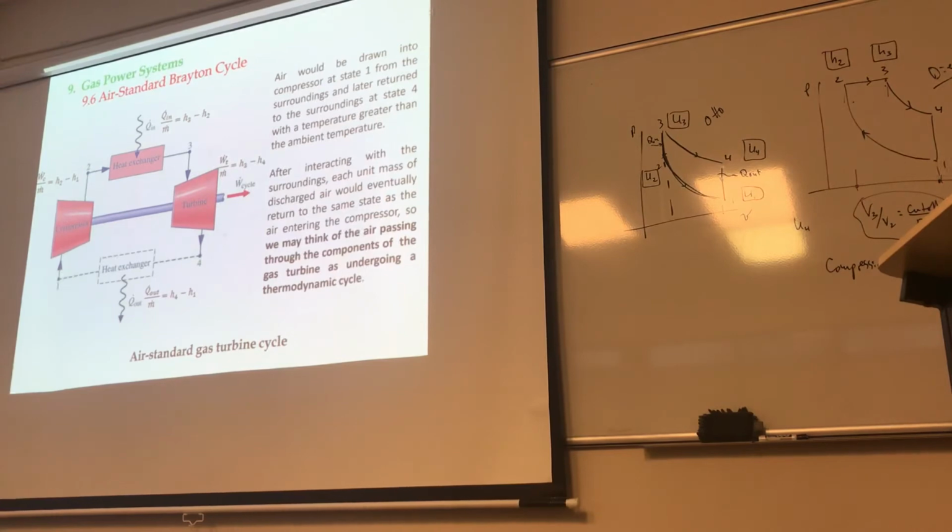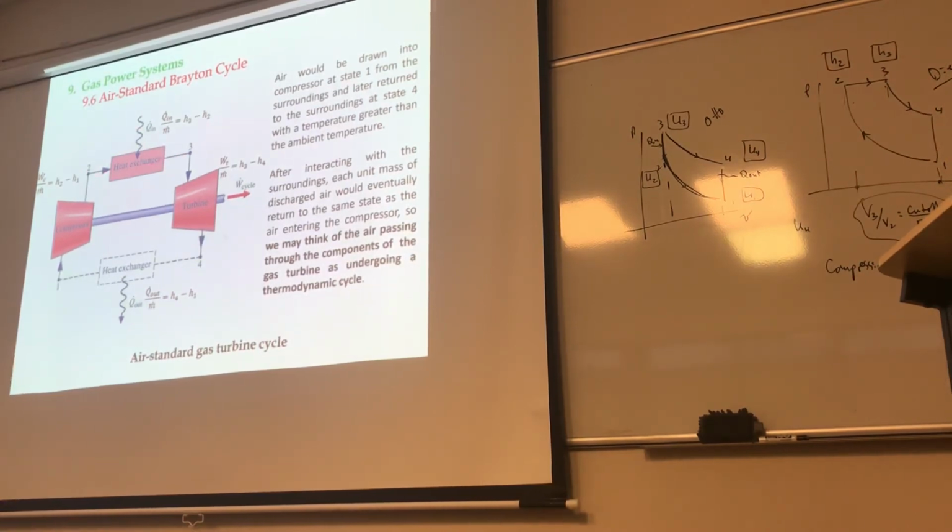Yes, because you're compressing, you're raising the pressure. So what is the difference between the H's, you think? It's more likely the work that the compressor is using up. Okay, how about here? Is H3 greater than H2? Heck yes, because we're adding heat. Whatever is going to come out is going to have a higher enthalpy than the heat in.